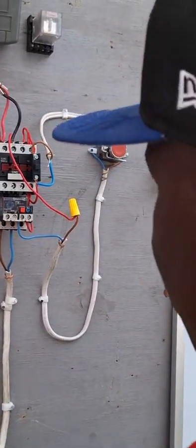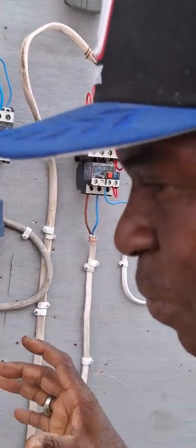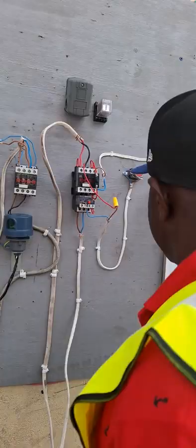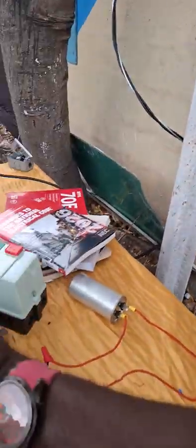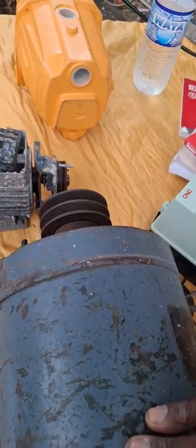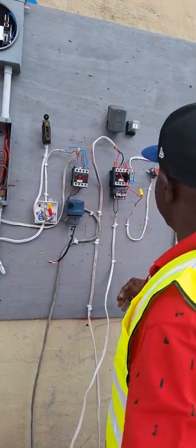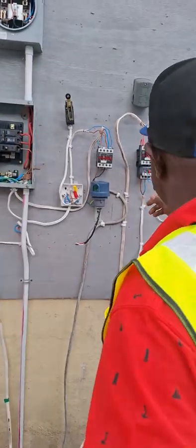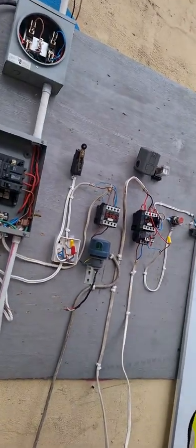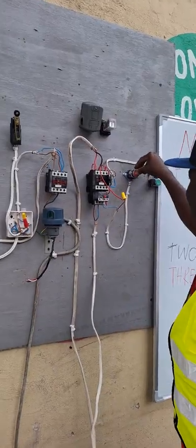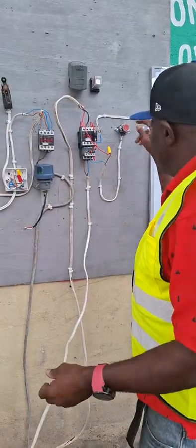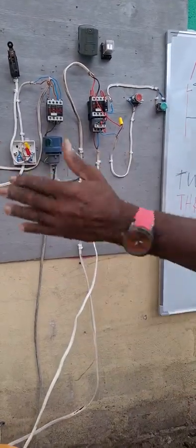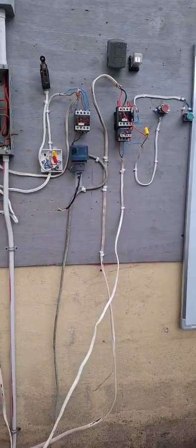Now we're going to start my 3-phase motor. I have this motor that can be started from 2 positions and also stopped from 2 positions. This one is started from this position. There's my motor running there. The coil closes, running my motor. Come here, I can open it and stop it here. Then I can go here, start it here, go over here and stop it. Anywhere you can start and stop it. This could be done from 3 to 4 different positions, and here's the representation of it.